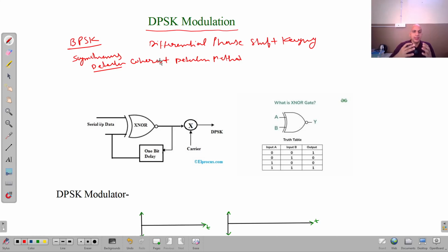So this makes the entire process very complex, and it is very difficult to design circuits for generating the matching waves. So the complexity of the circuit is very high, and it becomes a major problem with BPSK signals. Another problem is the requirement of high bandwidth. But the main problem is the coherent detection method, or synchronous detection method, of BPSK signals.